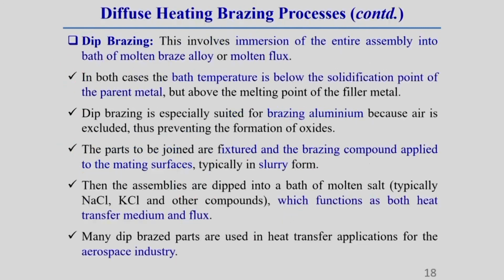Now, another category of the brazing process is called dip brazing. Dip brazing involves immersion of the entire assembly into a bath of molten braze alloy, or molten flux. The molten bath contains either molten flux only, or a combination of molten braze alloy and molten flux.